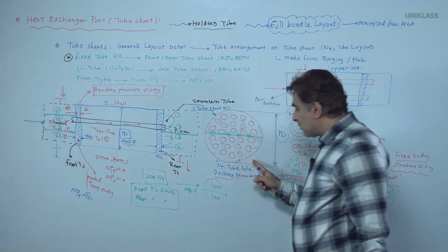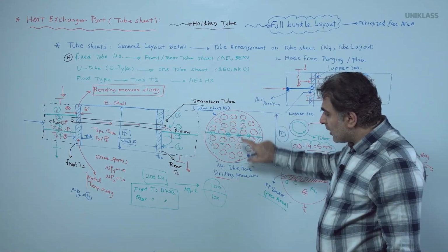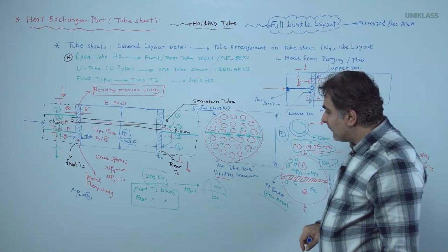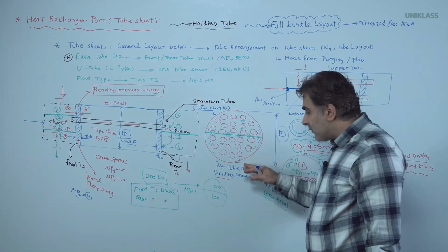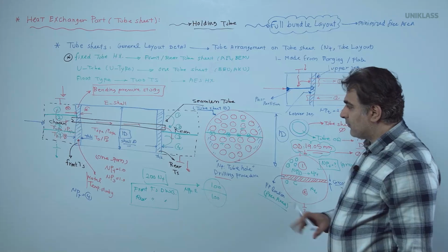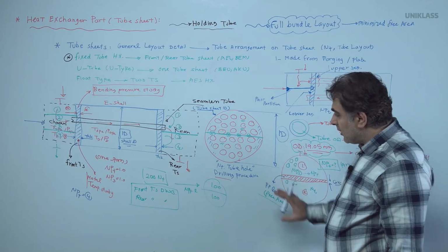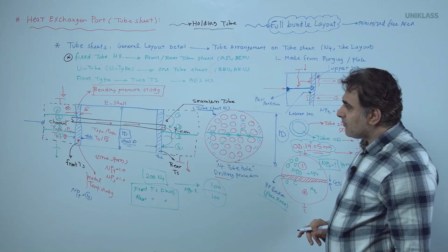The tube sheet layout says to us, see the tube sheet and how many tubes, how many tie rods, how many path partitions are available, what the free area is, and what the location of the additional parts is. Therefore, a detailed drawing is generated and says to us all of the information.